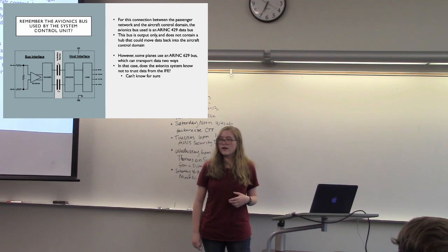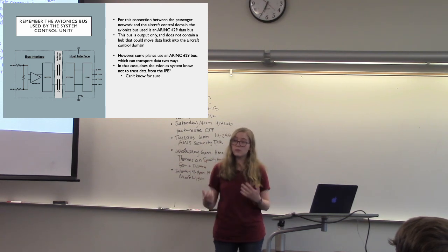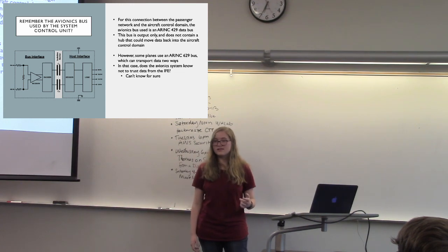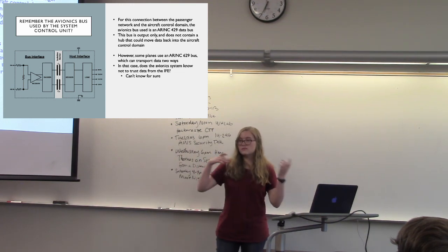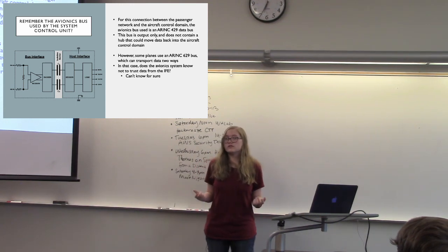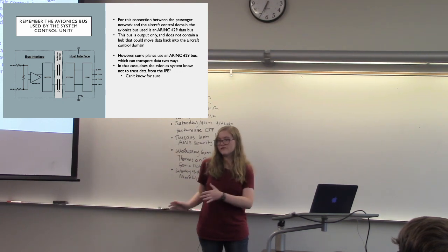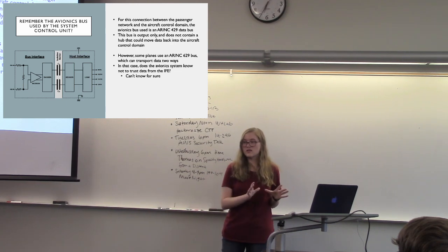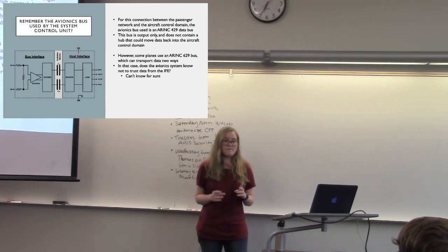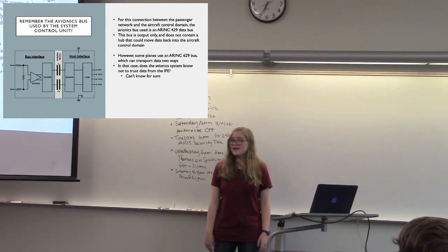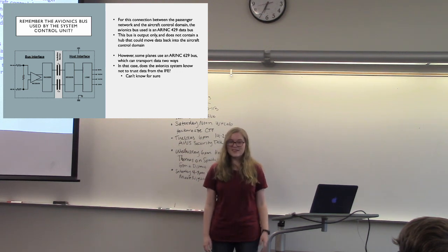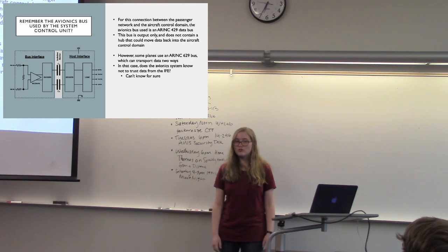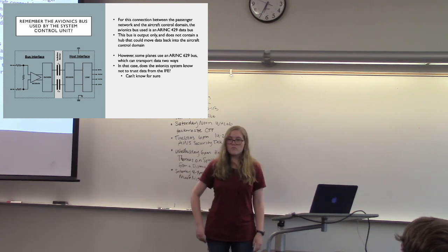And what I heard is, if it was on a plane with this specific data bus, then they can only send data from the avionics system to the IFV and not the reverse. So therefore, he can do whatever he wanted in the IFV, but nothing can move the other way. It's physically impossible. However, in some more recent planes, including the Boeing 777, those are ARINC 629 buses, which are two-way. So we can't say.